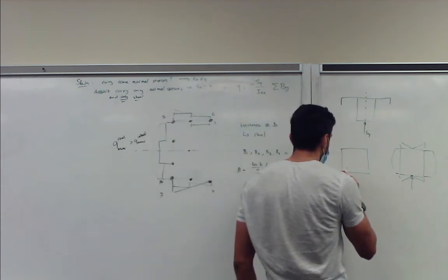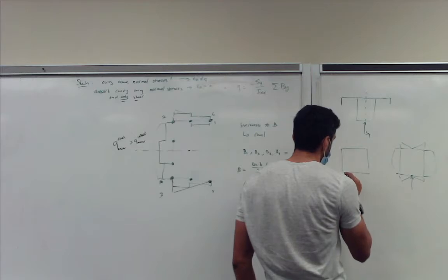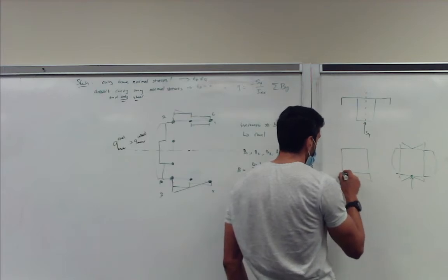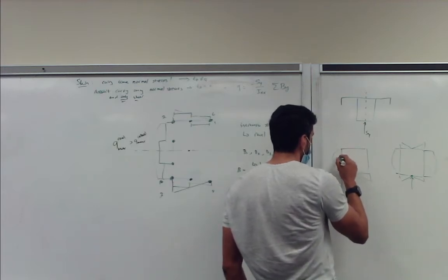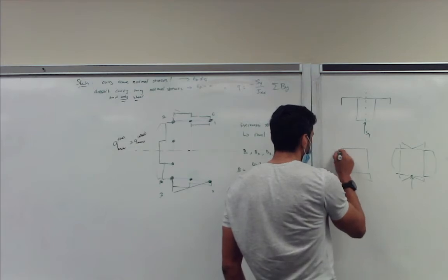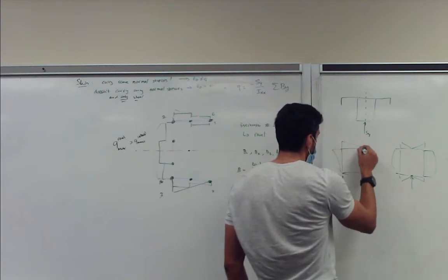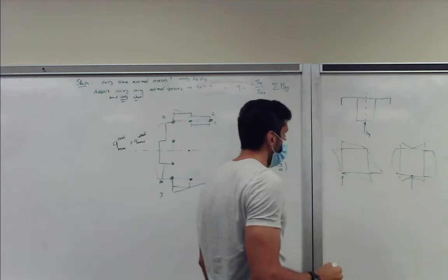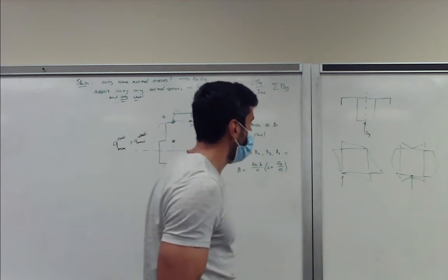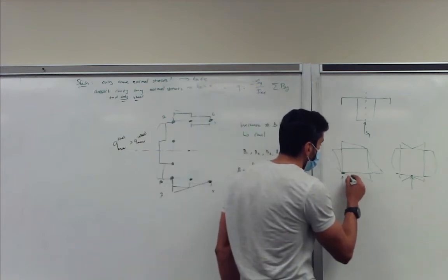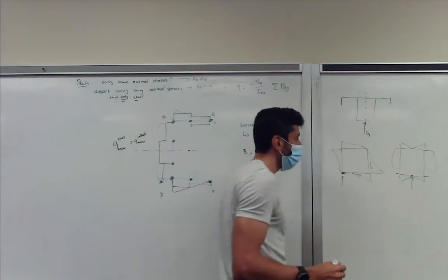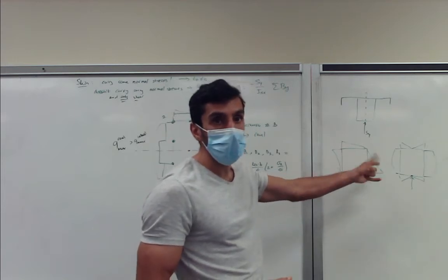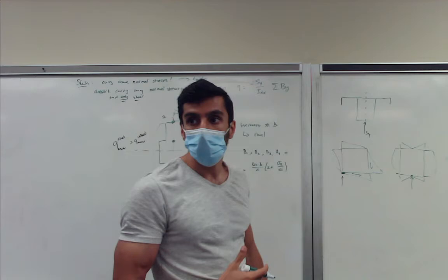Here, if you make the cut, it will be something more complex, because say you make the cut here, it will go like this. This will be quadratic, correct? Quadratic like this, and like this, and something like this. And if you now take the moments around this point, there will be two counteracting shear flows, but they're not equal in magnitude. So one of them will have a correction shear flow to it.